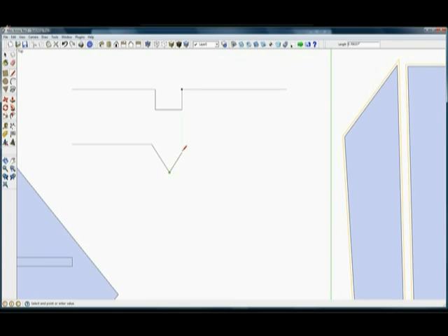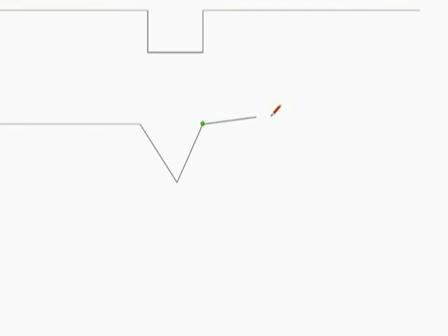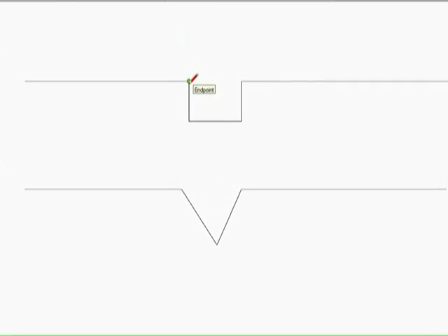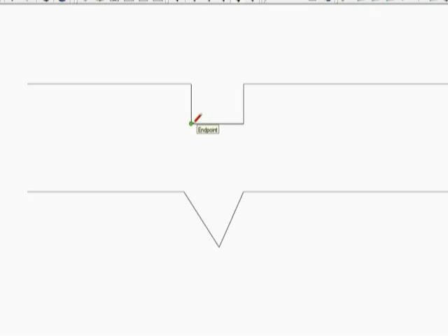And it'll continue on its way and plunge back into the material, and then continue down. So what we end up with, and I know that is very crude, but what we end up with is this case. This makes a nice strong tab, and it's really good with our 50% tab depth like we set.